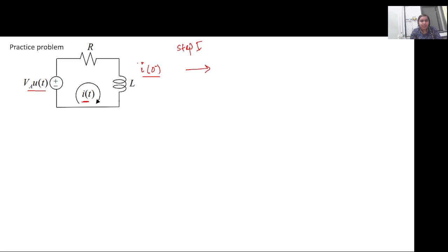When it is mentioned that there is some current flowing through the inductor L, the inductor can be drawn something like this. Sir had also shown this in the circuit: instead of writing the equation with an initial condition, that is sX(s) minus x(0), we can also write it as an inductor with a current flowing parallel to it.